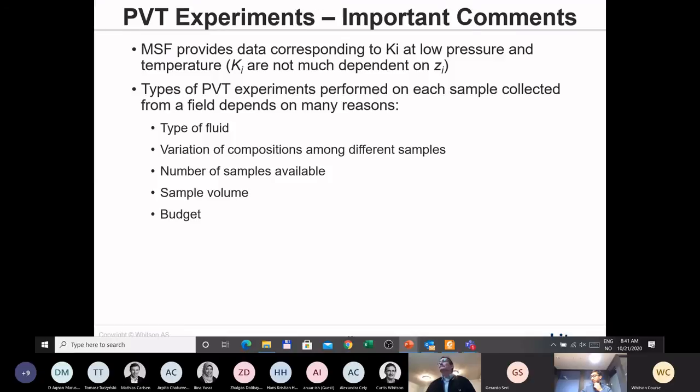So just as an example, since we are working a lot on common equation of state model development for these unconventional basins, and we have Eagle Ford, Montney, Permian, Scoop and Stack. There we generally see that you have a lot of PVT reports, and each well's producing well stream composition can vary from very lean gas condensate or even wet gas or dry gas to very low shrinkage oils.